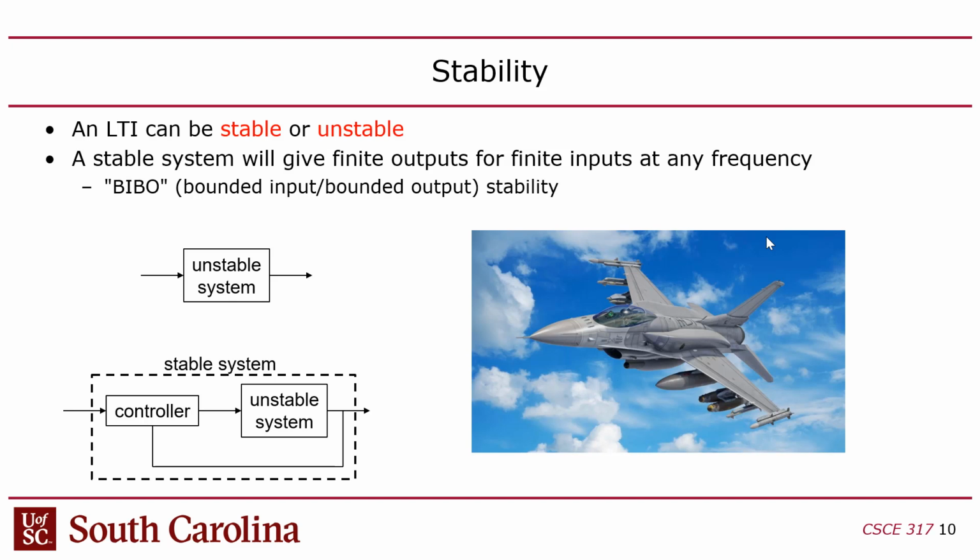A resistor, for instance, most people think of resistors as linear devices, right? They just follow Ohm's law, and the resistance is constant, right? Because you go and you buy a resistor, it has a constant resistance. It turns out it actually doesn't. Any resistor actually has a changing resistance. The more current you pass through it, the hotter it'll get, and the hotter it gets, it changes the resistance value. So it's mostly linear, but not exactly linear. But a lot of these things we want to model as linear systems.